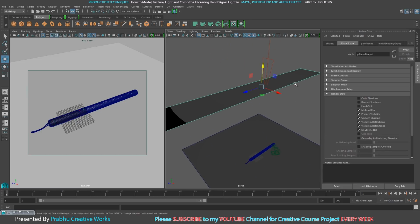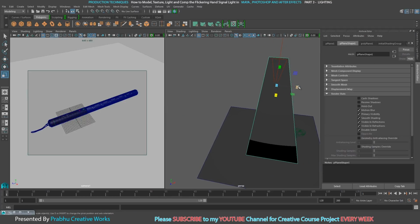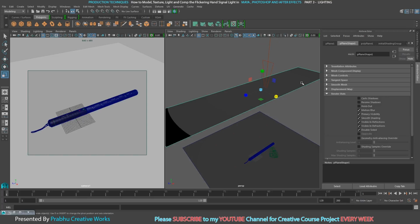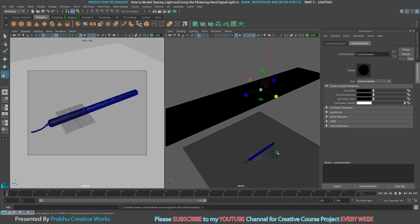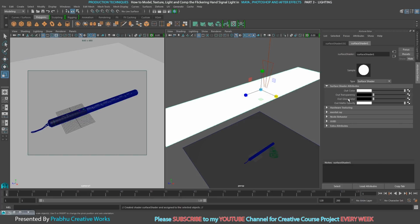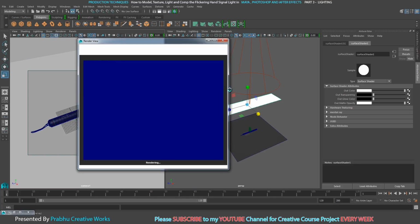receive any shadows. So I will apply some materials to this object, press R and scale much more like this. Right click and choose assign new material and choose surface shader and choose out color to pure white. So I will click over here and click render button.